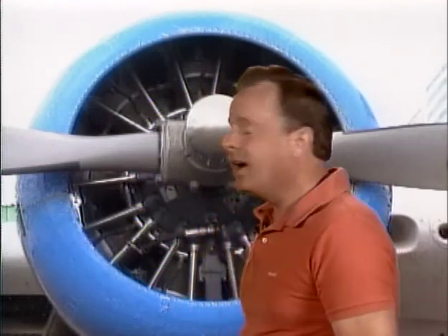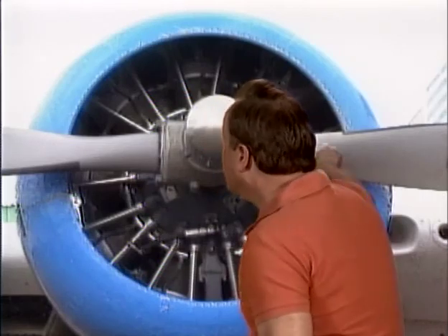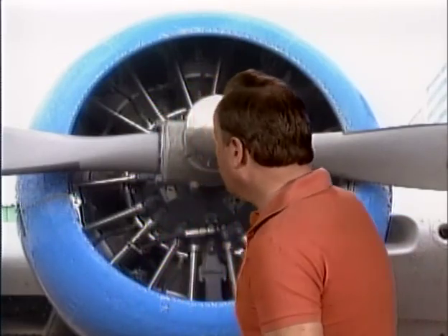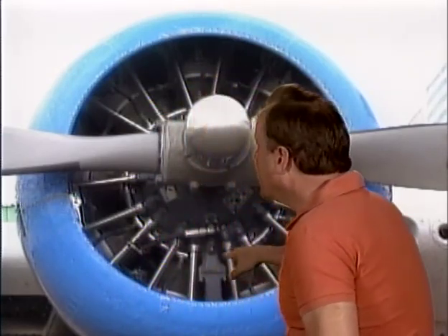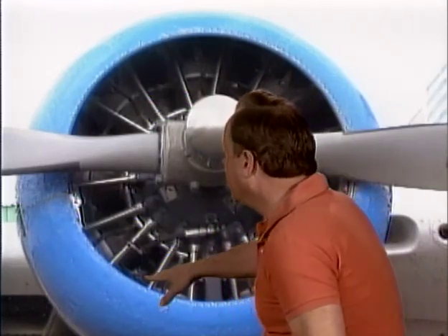Now, let's assume you have been working on an engine, you shut it down, and let it sit for more than about 30 minutes. Now, we're talking about a radial engine here, and that's particularly important. What should you do? Well, you should always turn the propeller through 3 or 4 revolutions to check for what is known as liquid lock or hydraulic lock. What happens is these bottom cylinders can fill full of oil or fuel, and you know that liquids are incompressible. So if you try and start the engine with the fuel down there, you can actually blow the cylinder off the engine, generally thought to be a bad thing.